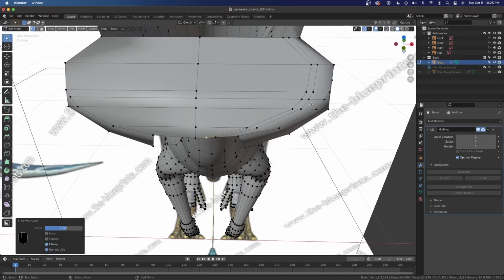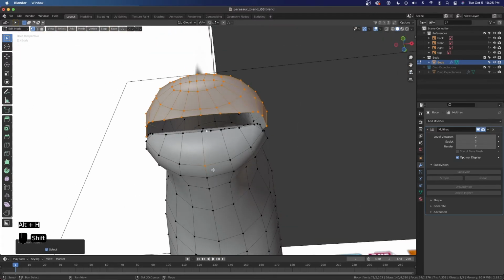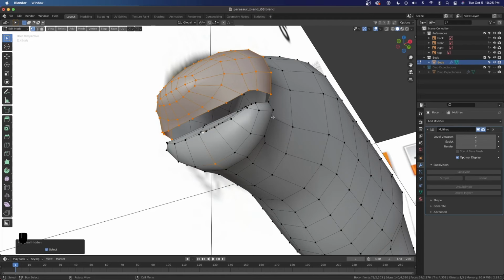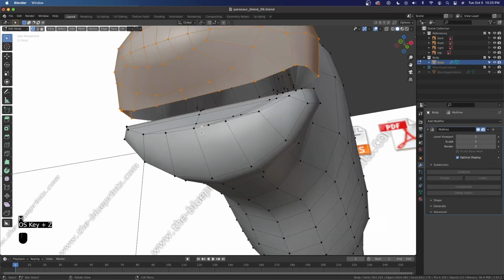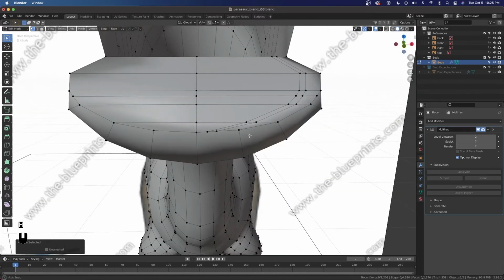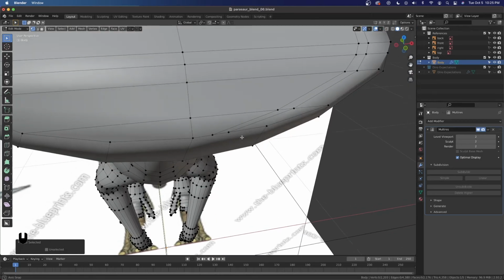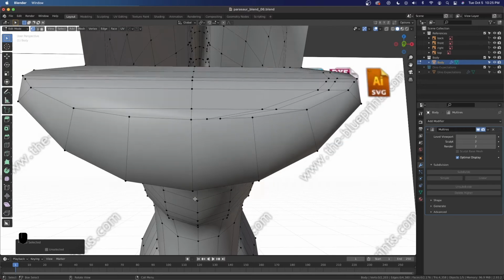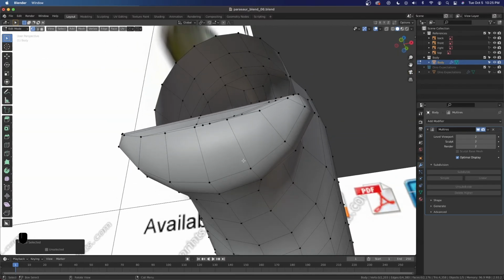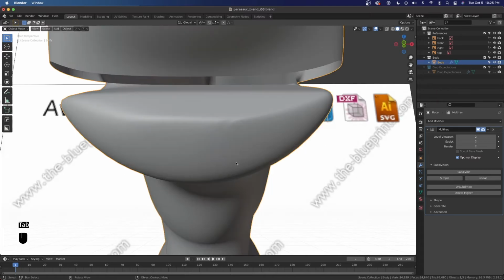All right, so now we can unhide. I just wanted to unhide that, but let's see. Just like that, hide the top mouth. Okay, so now we have another problem because we have 1, 2, 3, 4, 5, 6 vertices for one face, so that's not gonna fly with the multi-res.